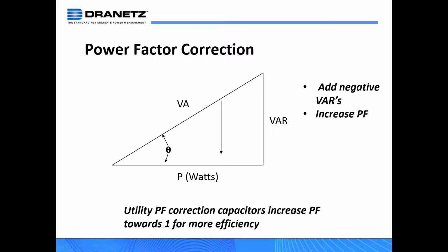So that works for them. It also works for you in your plants or in your application. If you have a poor power factor, and if you're charged a power factor penalty by your utility, this may be something you want to consider, to increase your power factor, either by power factor correction or other means, to reduce your energy bill and eliminate or reduce that power factor penalty.